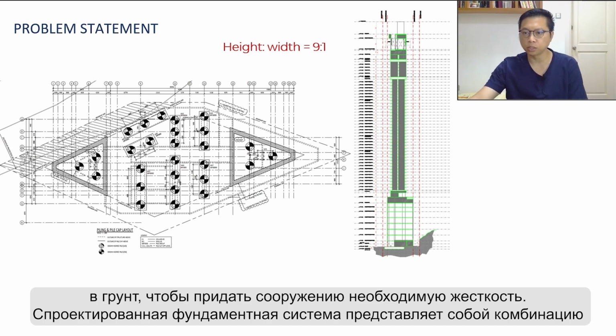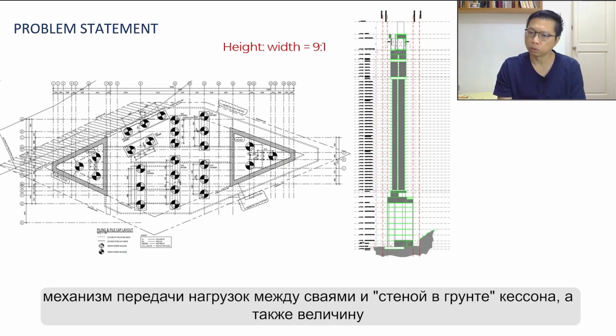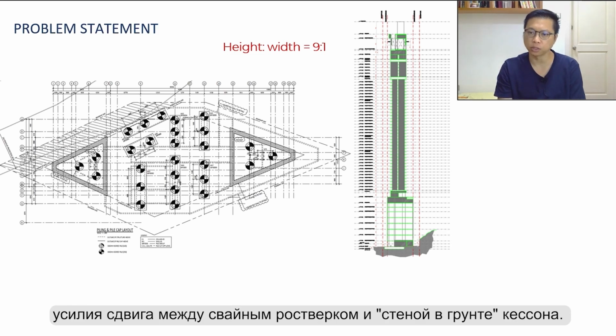The foundation system is a combination of coffer in triangle shape and big diameter bored piles within the coffer. We need to know the load transfer mechanism between bored piles and the diaphragm wall coffer, and how much shear force is developed in between the pile cap and the diaphragm wall coffer.